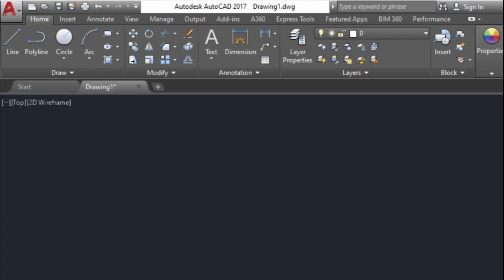And then we have our ISO draft, and object snap cursor, sorry, which is the object snap. The object snap contains, let's see, when you are drawing a line, end points, midpoint, center. So the object snap contains all those snaps. If you are in need of, let's say, midpoints, you click to activate midpoint. The midpoint is to show the middle of the drawing or the line that you have.